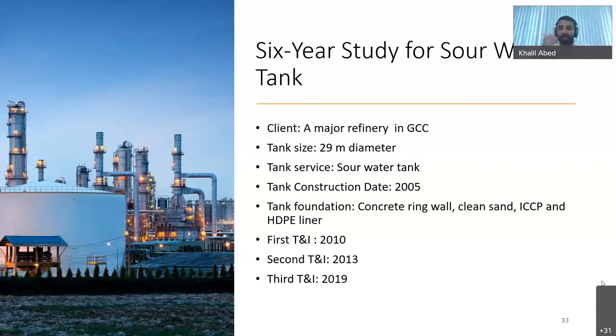And this is where they thought about utilizing vapor phase corrosion inhibitor to help them just keep the tank in service without replacing the entire tank floor, do the patch repair, and just help them keep the tank in service for the scheduled T&I, which was in 2019.